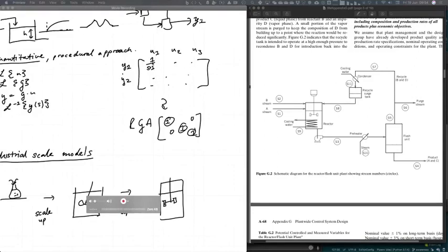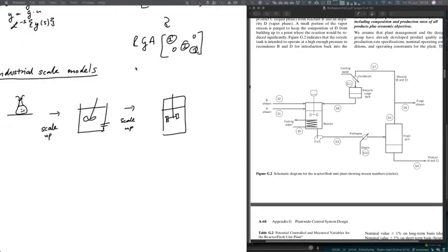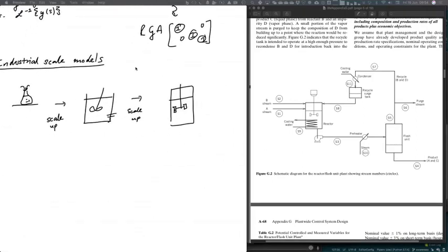So you can say, well, this input has this kind of effect on the output, this input has this kind of effect on the output. And what you see quite a lot in industrial control sessions is when control experts come in, they'll write something on the board that looks like a big version of this matrix, right? They'll say, okay, so here's U1, here's U2, here's U3, here's all the different outputs. And they'll interrogate this qualitatively. So they'll say, okay, if I do a step in U1, if I do a step in each one of these things, what will happen to each one of these outputs?